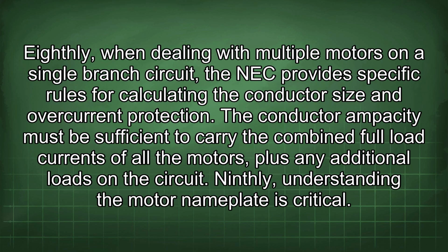Eighthly, when dealing with multiple motors on a single branch circuit, the NEC provides specific rules for calculating the conductor size and overcurrent protection. The conductor ampacity must be sufficient to carry the combined full load currents of all the motors, plus any additional loads on the circuit. Ninthly, understanding the motor nameplate is critical.